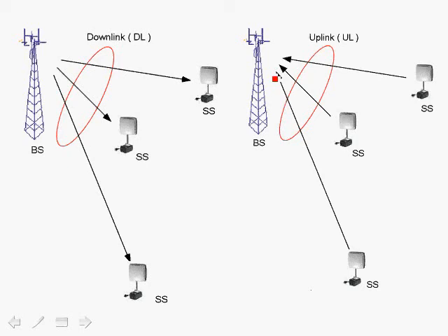And we indicated that through initial ranging, the base station can adjust the timing offset for each subscriber so that when they transmit, they are received in alignment. And we mentioned, of course, the range of 25% of the cyclic prefix. Another issue, of course, is power management.